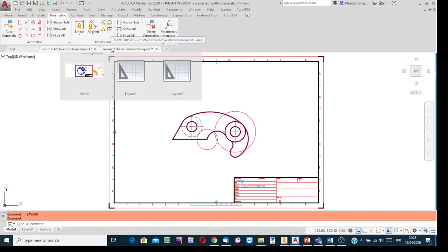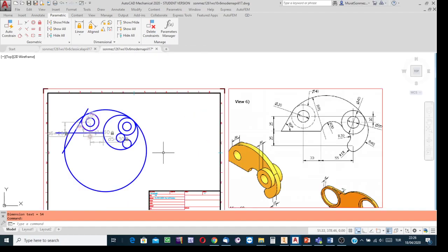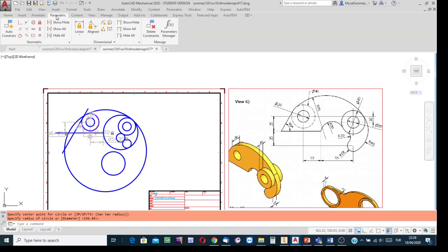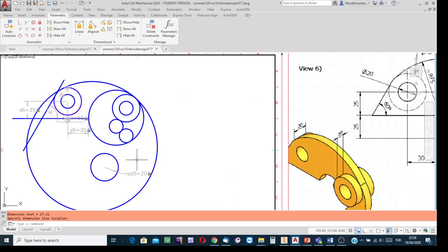But in applying the modern method, there is no need. To have in the end such a circle arc, create the circle arbitrarily at this side. Create the circle arbitrarily and then input its parameter. Radius: click on this button, indicate the circle, click, and the radius is 20. After sizing it, check whether it is still at the suitable side, the correct side. Yes, the answer is yes.